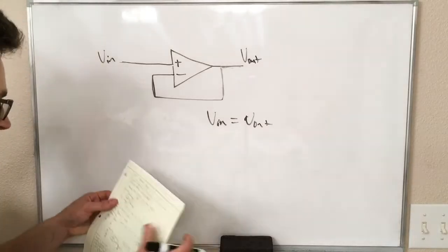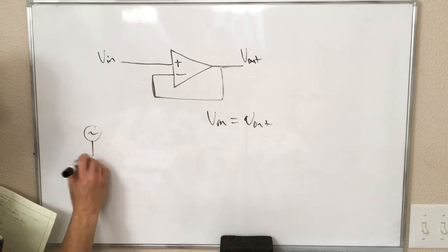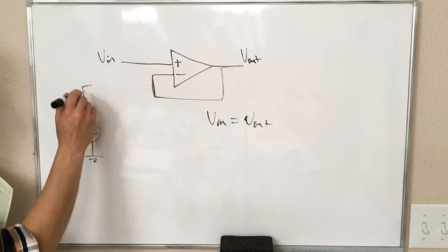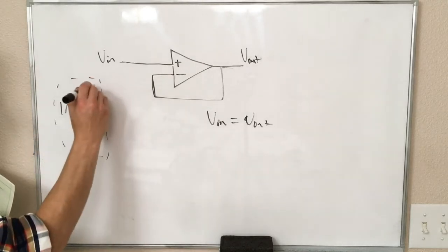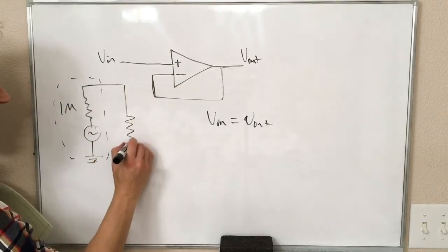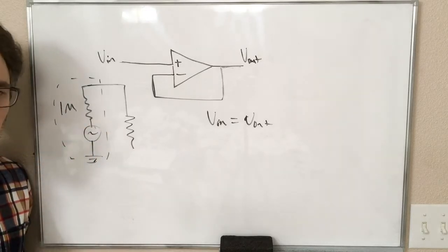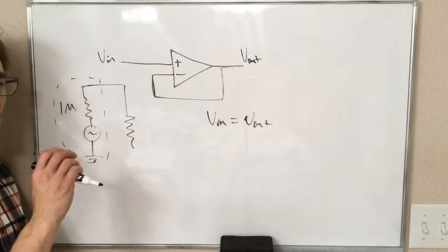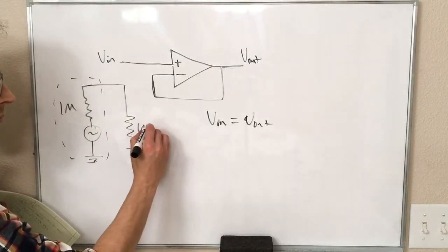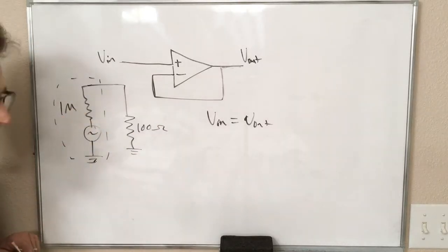So for example, if we had something that looked like this, some signal here that has a source resistance of 1 mega ohm, so something really big. So this whole thing is our voltage source, right? And we try to connect this to a load. Maybe this is a signal coming from some sensor, or a signal coming from your computer that can't output very much power, but you still need to be able to do something with it, right? And your load is 100 ohms. You need to run a motor or turn a light on when this happens, or something, right?